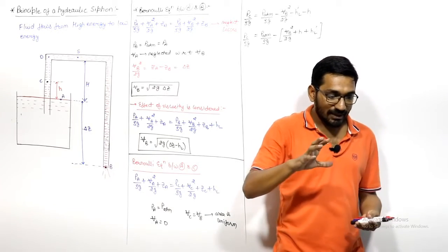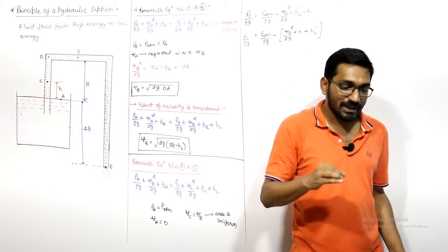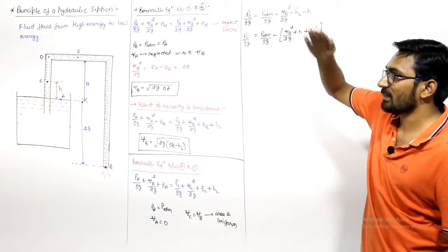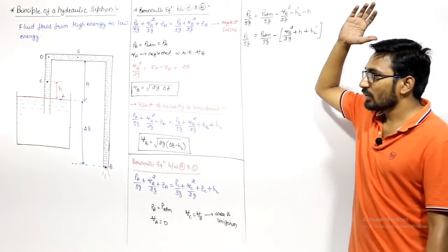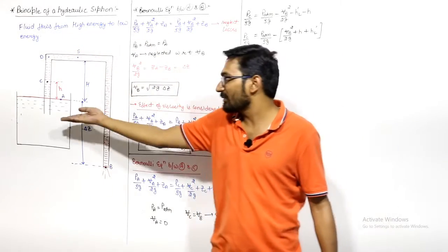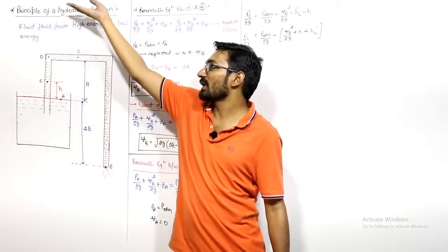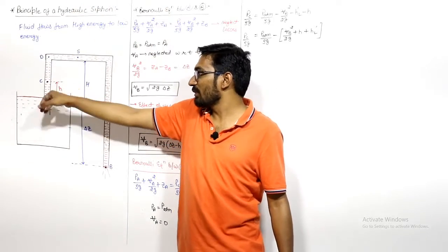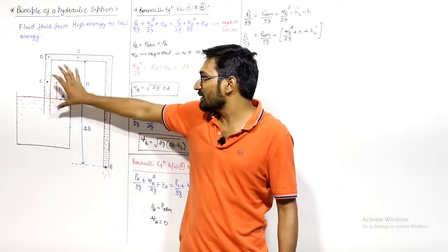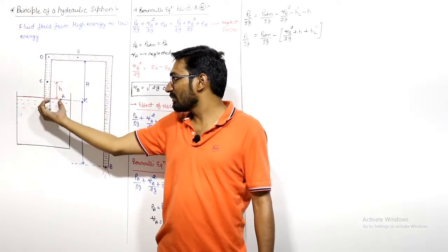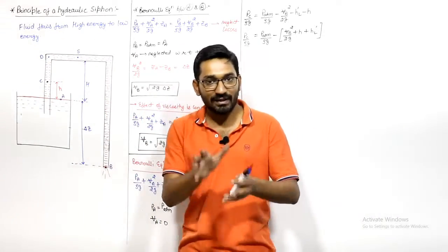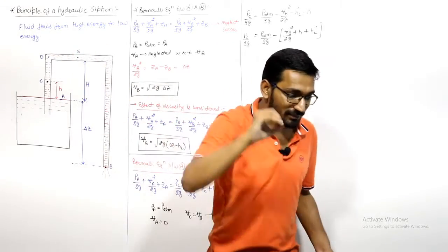So now we can say that the minimum pressure in the flow, right? If the fluid is flowing in this upward direction, the pressure is continuously decreasing, right? So where the pressure is minimum, the pressure is minimum at this top point. As the fluid is flowing in this direction, it has to increase its potential head more. If it is flowing from point A to point D, then it has to increase this much amount of potential energy. It has to overcome the friction from point A to point D. So more pressure will convert into these energies. So the pressure at point D will be minimum, right? At point D, the pressure will be minimum.